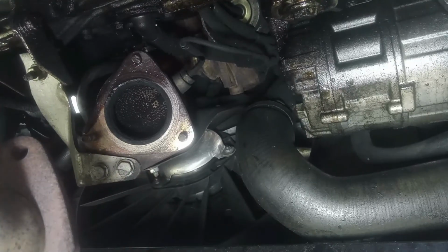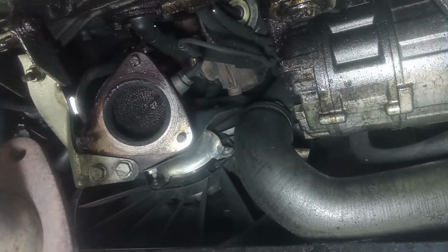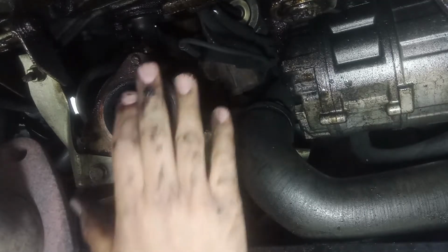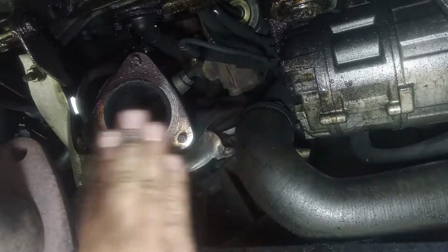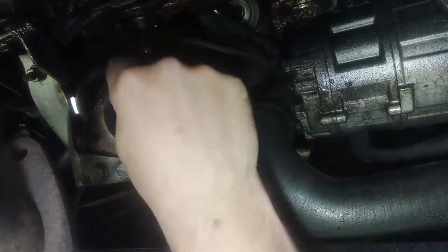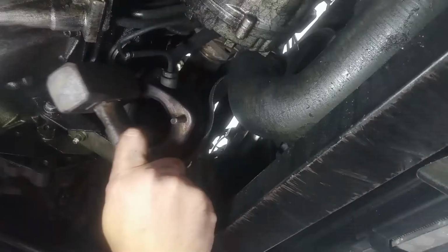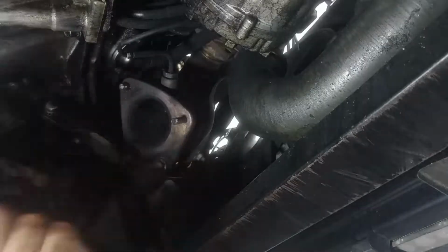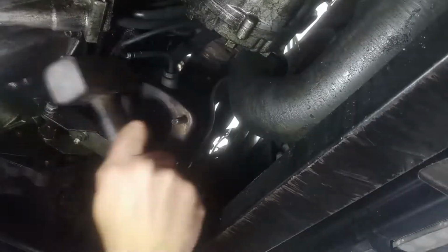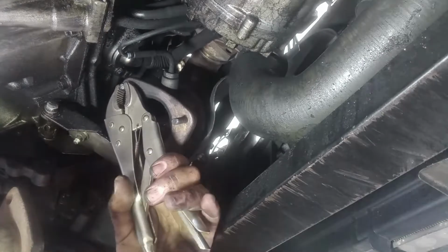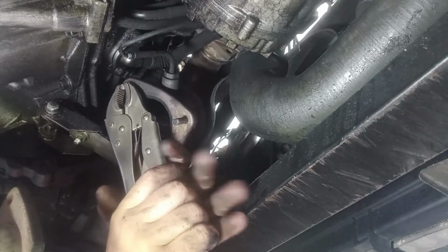You really cannot ignore exhaust leaks. I hated them because of the 75, but you really cannot ignore them. They really have to be flawless, the exhausts. So I'll try to do it here with a file, to file it down to be perfect on the top surface. In that way I can drill it down, possibly, maybe, let's see. Jesus Christ, this engine is filled with carbon on the exhaust. No wonder the DPF is suffering.